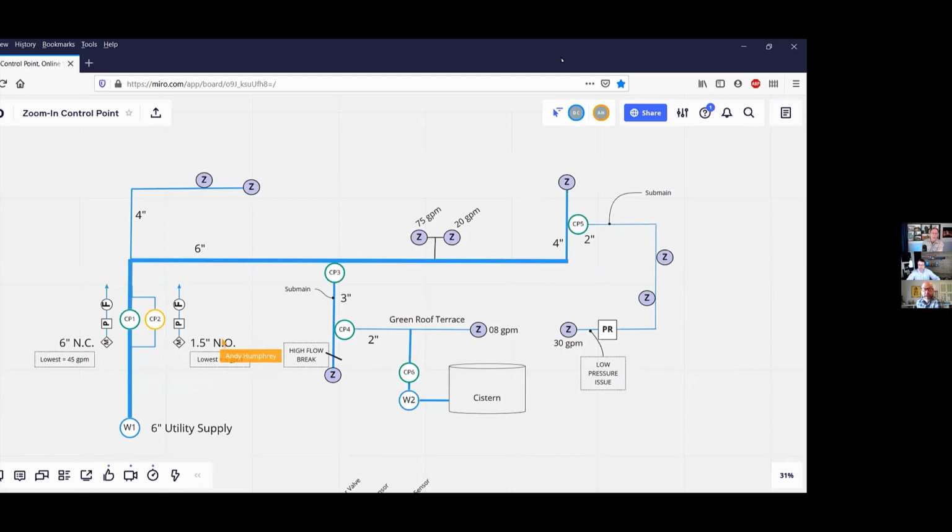Yeah, this leak detection concept I really love. I mean, the idea of anything 2-inch and larger, if you had a 1-inch bypass, the resolution you're going to have on that is so much better than what you might normally have with your larger sensor. Yep. And then Don's got a question about the number of control points.